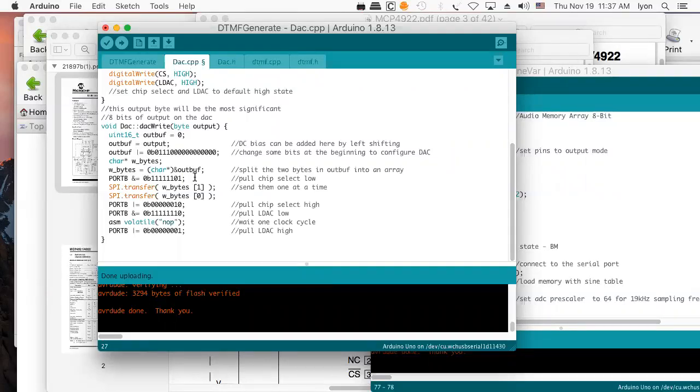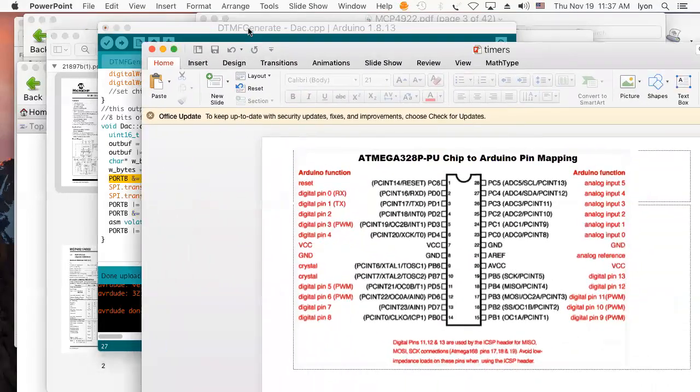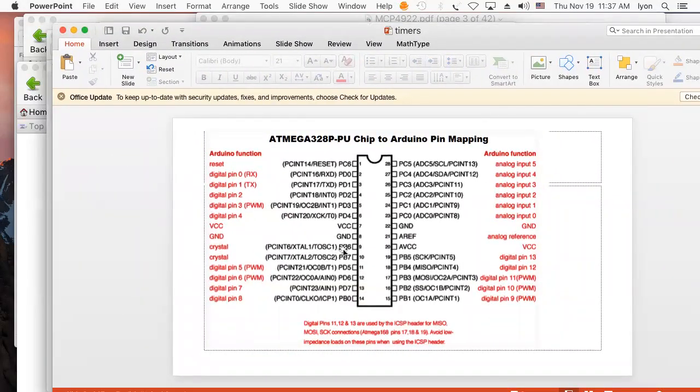And we can kind of see how that made life a little bit easier for the computer. So at this point now, we're really down into the bit flippy part of writing out to port B. If you go back and look at the chip layout and where port B is, you can see port B is actually distributed in several places. If we start with port B0, port B1, port B2, 3, 4, 5, and then it jumps all the way over here to 6, and then goes down to here to 7, it's kind of all over the place in terms of where the pins are. I'm never sure why they put things where they put them, but that's what they're doing.